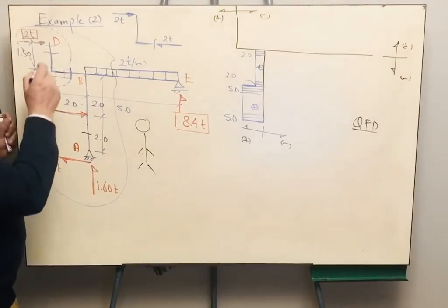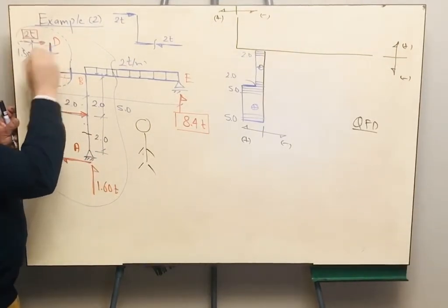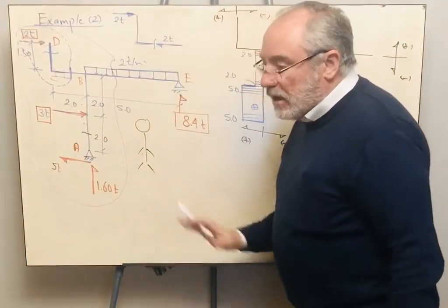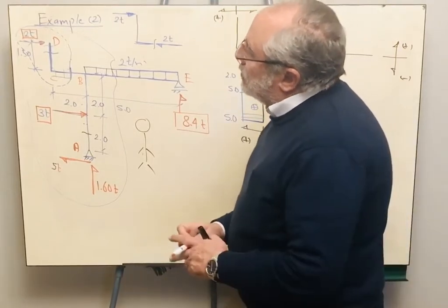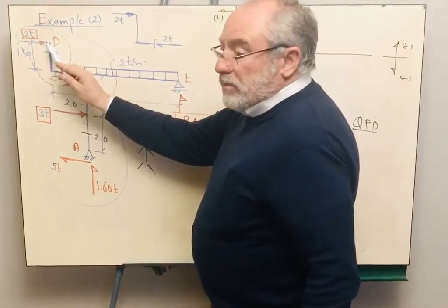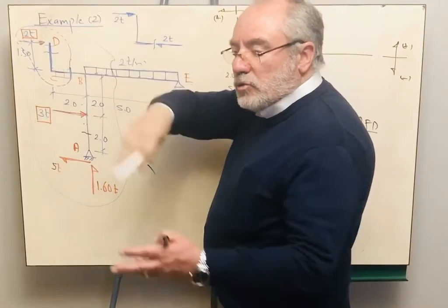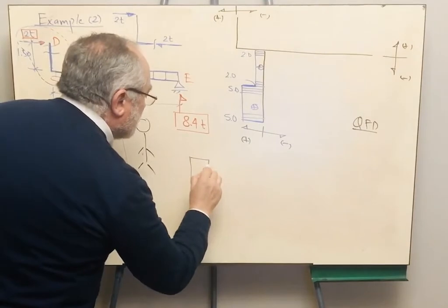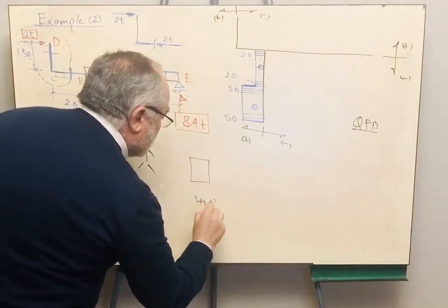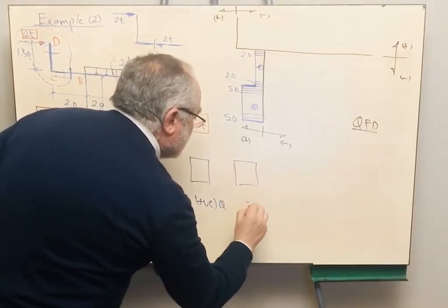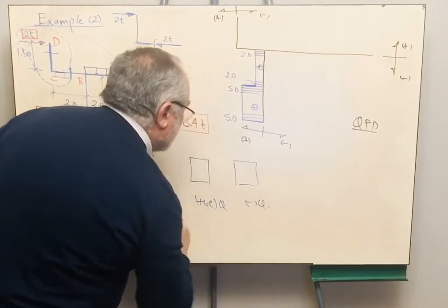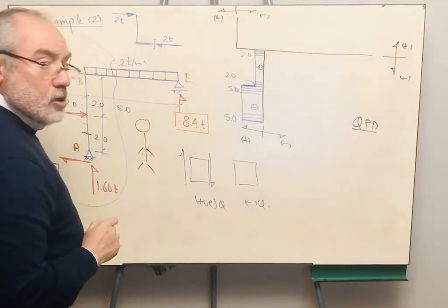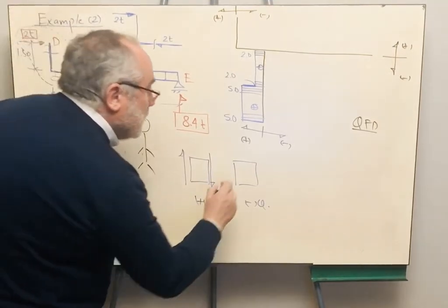How about the part CD? Again, we are standing here. Okay, we are standing under the frame. Now, I want to start from this point, but this point is on my right hand side, so it will reverse everything. You remember the positive shear. This is the positive shear, and this is the negative shear. Okay? The positive shear is on my left hand side and upward, or on my right hand side and downward. But the negative shear is vice versa.